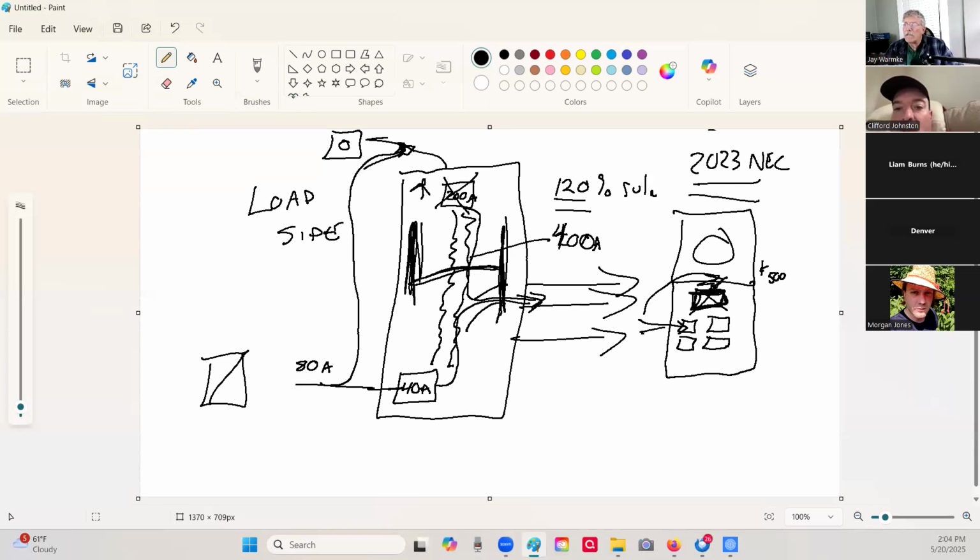Any sub panels, these things are not connected together. They're separated. The ground and the neutrals are separated. There's only one place for making that bonded connection, and that's in your main disconnect panel. Well, if you add this box out here, it's now your main panel. And you're going to bond together the neutral and the ground.